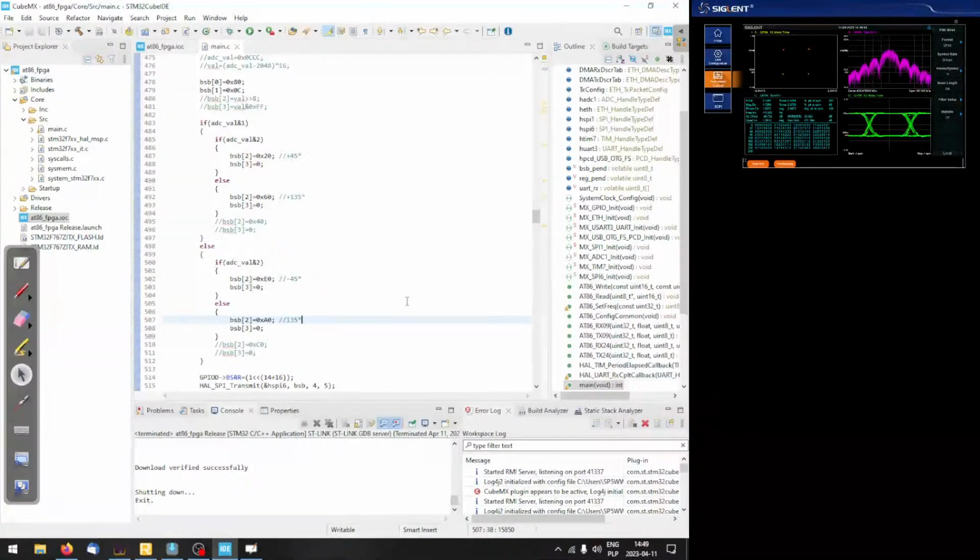So we don't actually apply any filtering. If you take a look at the spectrum analyzer, there is the filter setup, where the instrument can be told to filter the baseband. We told it not to filter it because we expect the signal to be just a staircase. But the next step would be to apply some root raised cosine filtering for the baseband and actually use this.